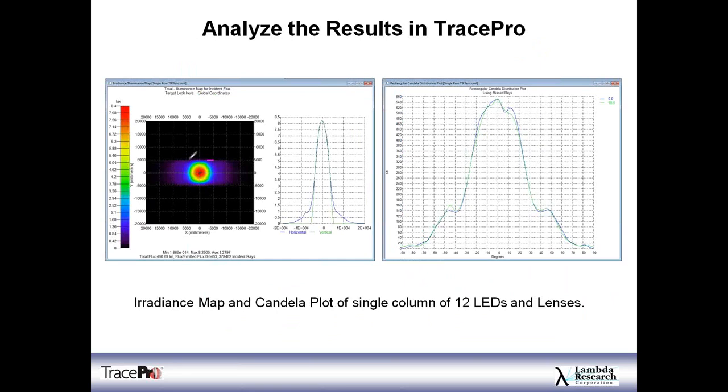We look here at our target now. We've filled in a little bit more. Our lux value is now up to, at least for the center, about 8.5 lux. If we look at our max, it's 8.3. Our efficiency is the same, and our total flux is now up to 470. And you remember our goal for total flux was at least 2,000 lumens, and we wanted to keep at least 14 lux in this target area.